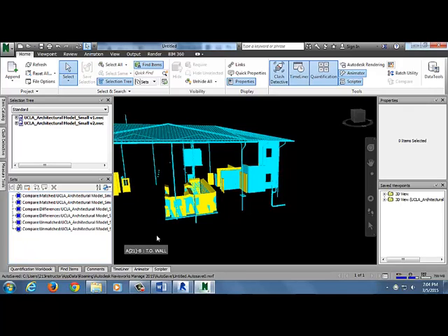So if you go to shading mode, it's weird. Sometimes it just kind of goes to shading for you, but sometimes it doesn't. I thought it always did. And if you want to get rid of those grid lines, if they annoy you, the green and the red grid lines, you can get rid of them by going to View and then Show Grid Lines. There you go.